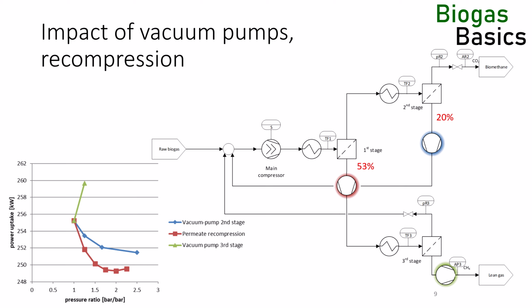gas. The installation of an additional blower might improve the performance of the plant, but it adds another process unit that can break. From the operational point of view, I would rather add more membrane modules than an additional process unit to save on power demand. Next, we investigate the impact of gas qualities on the optimal operation of the biogas upgrader.